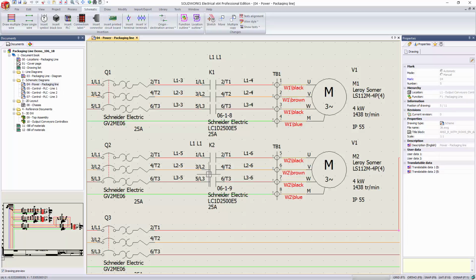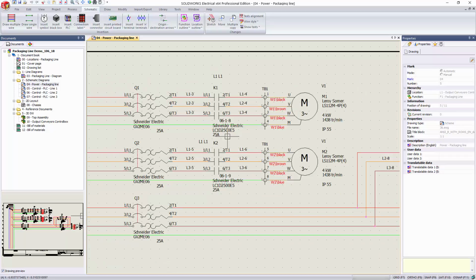Maybe also someone wants to add some things to the system that's going to add a page in our schematic. Right now we have page 4, 5, 6, 7. Let's say we want to add in a new page right there in between page 4 and 5. That's a lot of things that are going to have to get updated. All the page numbers, all the references to wire numbers, page-to-page connections, all of those. Let's see, something else that could cause a change. Maybe we're going to add a clip-on component onto one of these relays so that we can actually add more circuits.